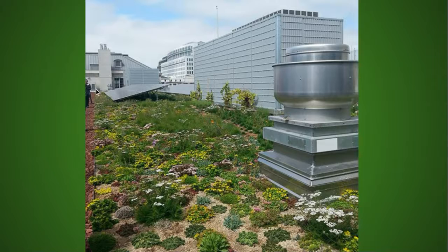And again, you can see there's people on this, the HVAC systems and solar systems located on the roof, and then the vegetation there as well. So let's talk about some advantages and disadvantages. The advantages of a green roof are you have reduced runoff from your building because you have water retention built in. Another thing is with this additional thermal mass and the plants on top, it absorbs a lot of radiant energy from the sun that doesn't get passed through into your building. So your internal temperatures are more stable below a green roof.